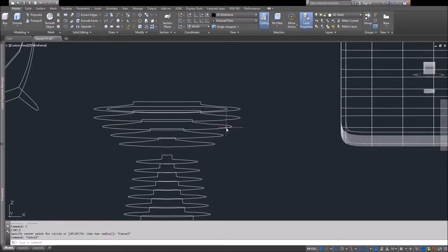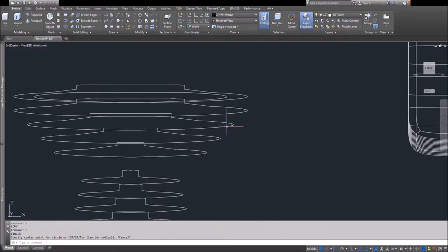So one of the things I'm going to be doing here is, again, I'll be shifting some of the profiles up. I'll be offsetting them inside a little bit just to get a more rounded shape as opposed to just a straight line sloping shape. So again, at this point it's easy to do. They're just polylines, and I could very easily manipulate them without too much effort. But you do have to look at it and get a sense of what it's going to look like.